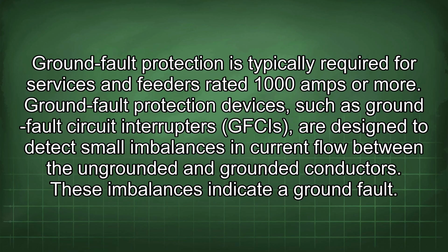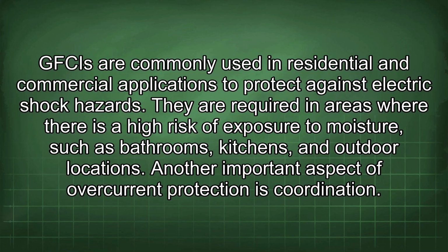These imbalances indicate a ground fault. GFCIs are commonly used in residential and commercial applications to protect against electric shock hazards. They are required in areas where there is a high risk of exposure to moisture, such as bathrooms, kitchens, and outdoor locations. Another important aspect of overcurrent protection is coordination.